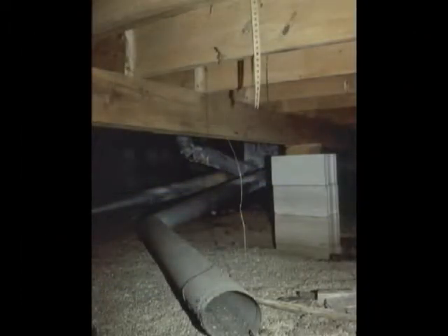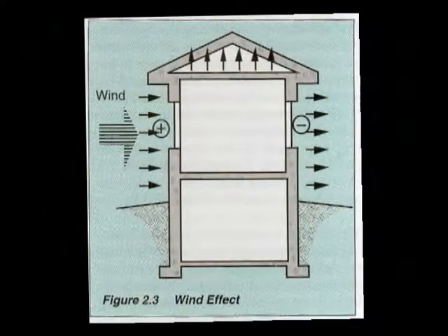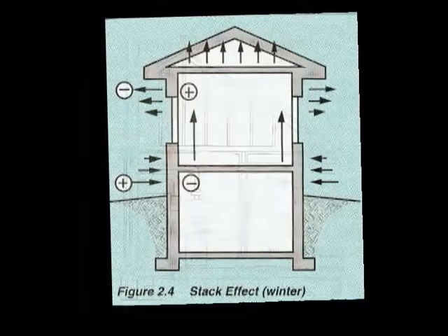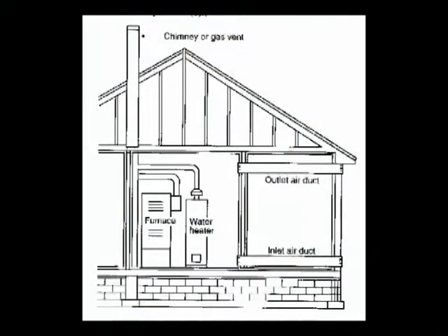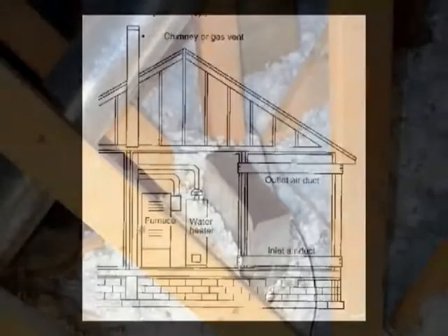Supply duct leaks in an attic or crawl space can depressurize the house and possibly the CAZ, thereby causing draft problems. The wind and stack effect on the building can also create negative pressures in the combustion appliance zone. For example, code-conforming combustion air intakes on walls that are opposite the prevailing winds can actually suck air out of a CAZ.